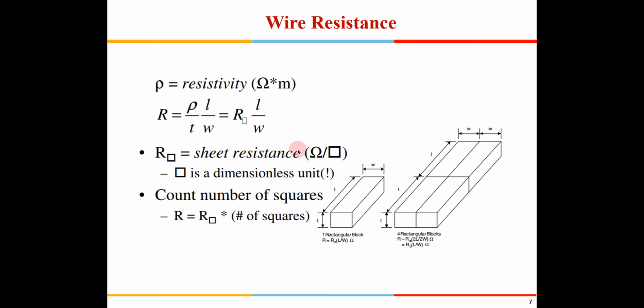Now specifically for VLSI chips, we see that this T is not available to the designer, right? It is already pre-decided by the technology, that is, what the thickness of the wire is going to be. The backend designer who is going to make the layout only draws the wires interconnecting. He has the flexibility to change this L and W. So T is not a design parameter available to the people who design the layouts. That is a fixed parameter set by the fab lab.